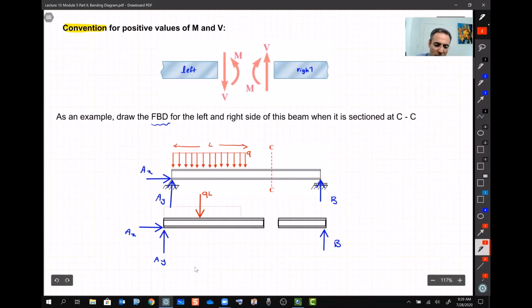So far, this is all external loads, okay? Exactly as we see things, the external loads, we put them there, except for the distributed loads, which we put the equivalent. Now, when I'm sectioning this portion, we know at this cross section something is going on here, which we discussed, right? We said it's going to be a V and M at any cross section.